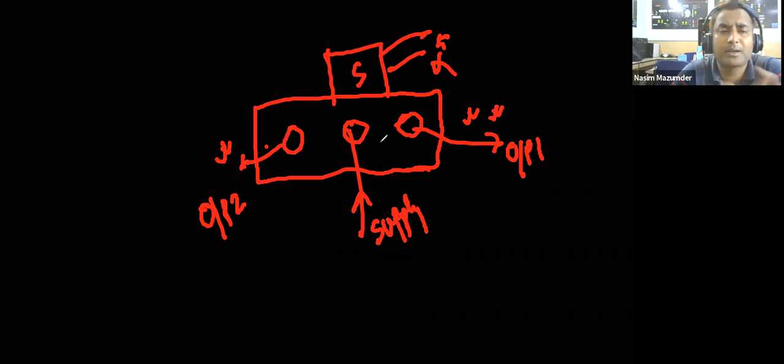Based on our requirement, we can choose whether I am going for a single acting solenoid valve or a double acting solenoid valve. If you are using a power cylinder, then definitely you better go for a double acting solenoid valve, else you can go for two single acting solenoid valves.